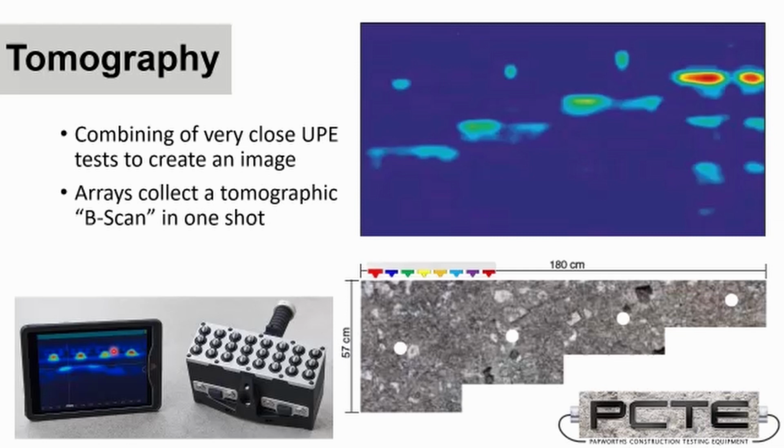The echoes are recorded and processed using tomographic techniques to produce a representation of the internal structure, showing thicknesses and targets inside, primarily voids. It'll be most sensitive to voids, but there's also some evidence of reinforcing steel and other targets within those structures.